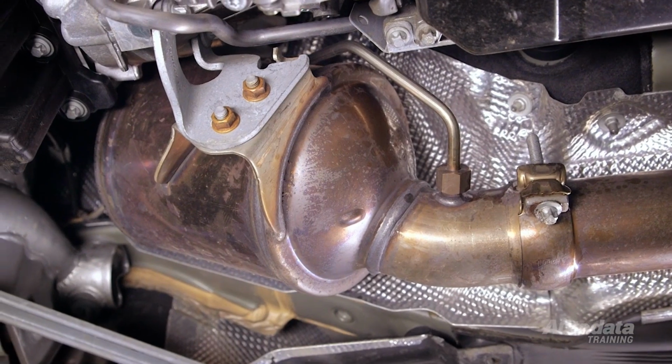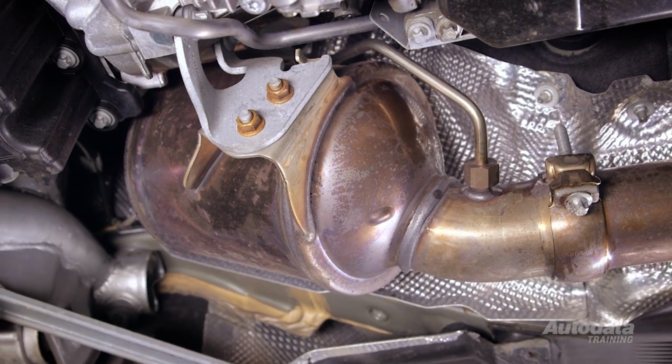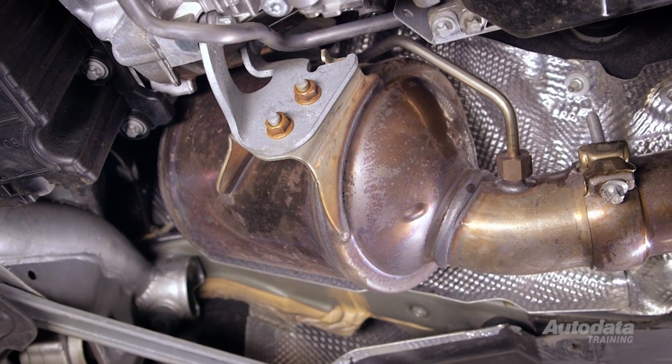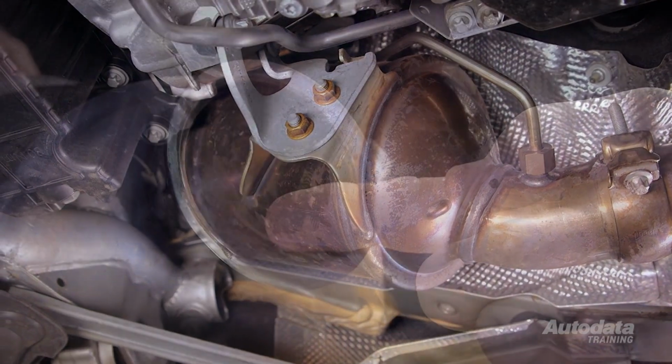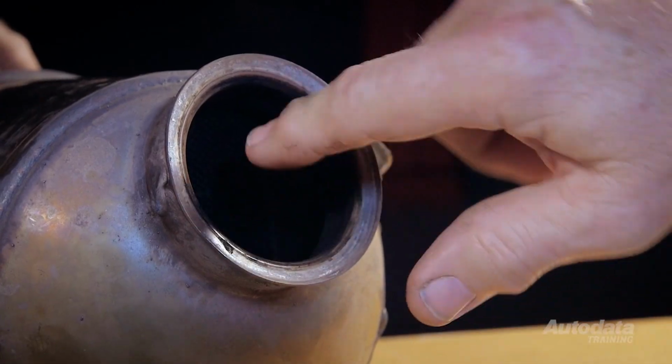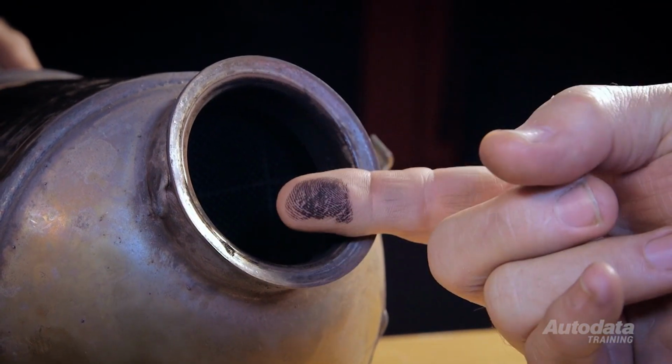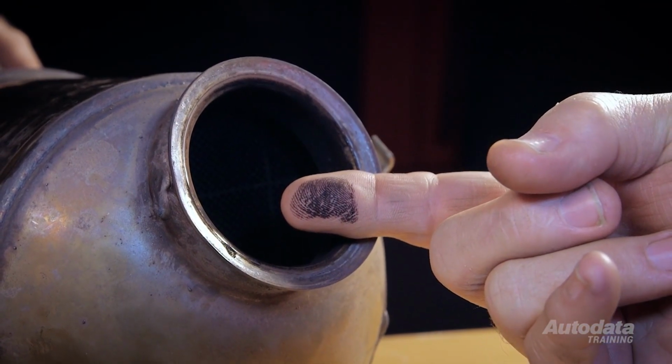If the fault code suggested a DPF with an excessively high soot content or blockage, then you should only perform a forced regeneration once the ECM, electrical circuit, sensing pipes and sensor have been confirmed as serviceable. If the service regeneration proved ineffective, then the DPF can be removed for a closer inspection. If the DPF shows any sign of damage or deterioration, then it should be replaced.